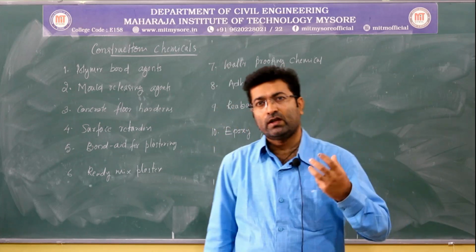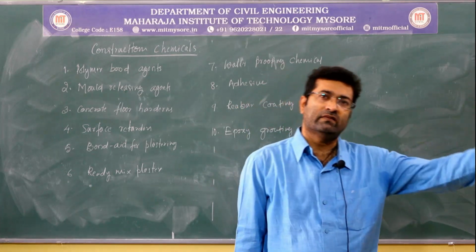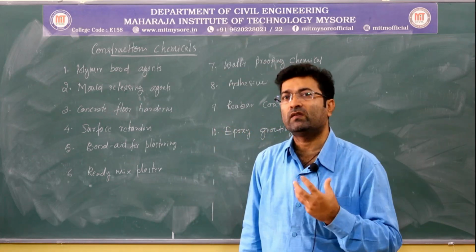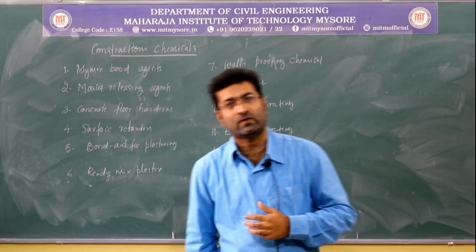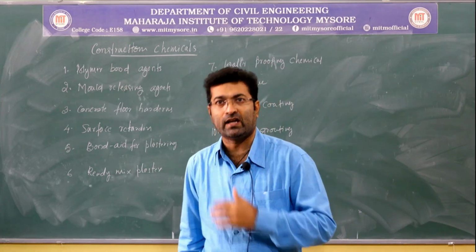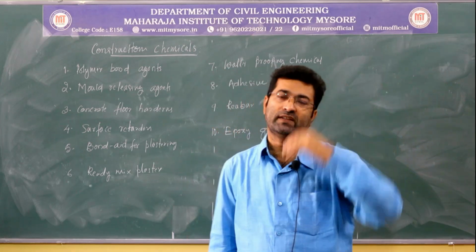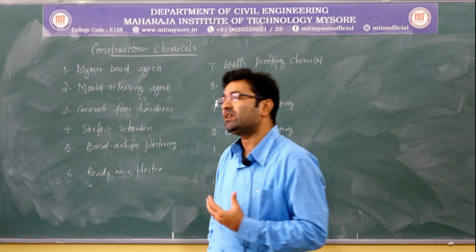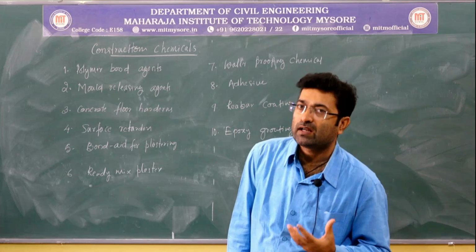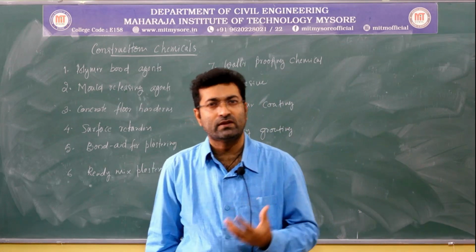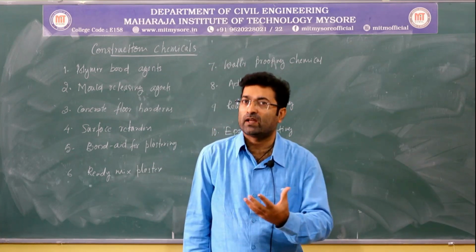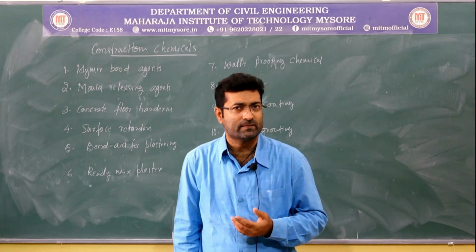Let us assume that the ready mix plant is somewhere in the nearby city, and the construction activity which is happening is far away from the city area. So, the ready mix which I need at the site needs to be brought from the city, right. As we all know, concrete has setting times. It starts hardening after the initial setting time like 30 minutes or 40 minutes, and it has a final setting time like 600 minutes, that is 10 hours, right.